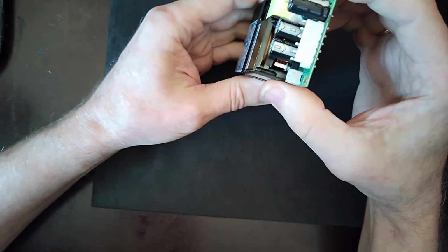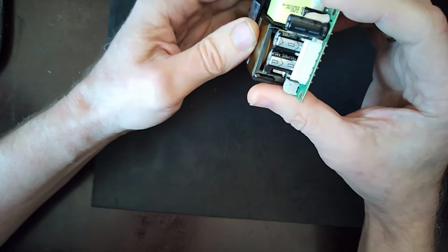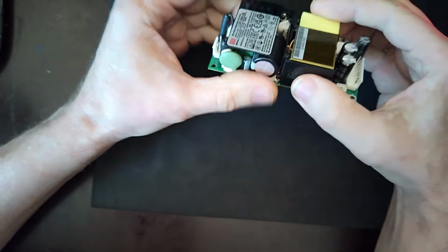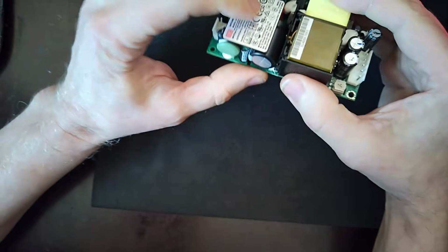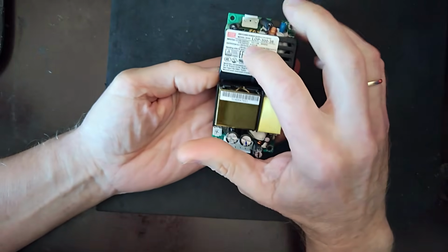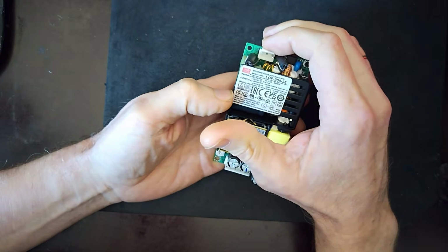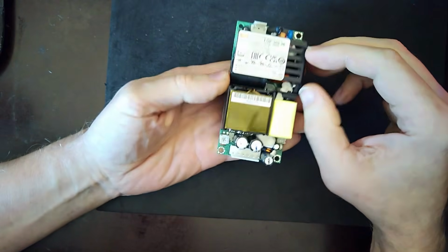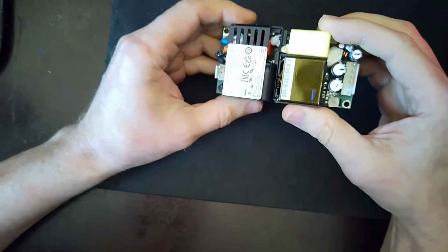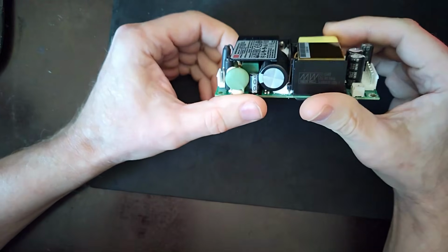This is really a state-of-the-art engineering system, and you can see here it has all those specific architectural windings of this power transformer. It is an LLC power supply and it has PFC. And how it works, that PFC is multiplying the input from 110 or 220 to 400 volts, and then this power part is working from PFC stabilized at 400 volts.